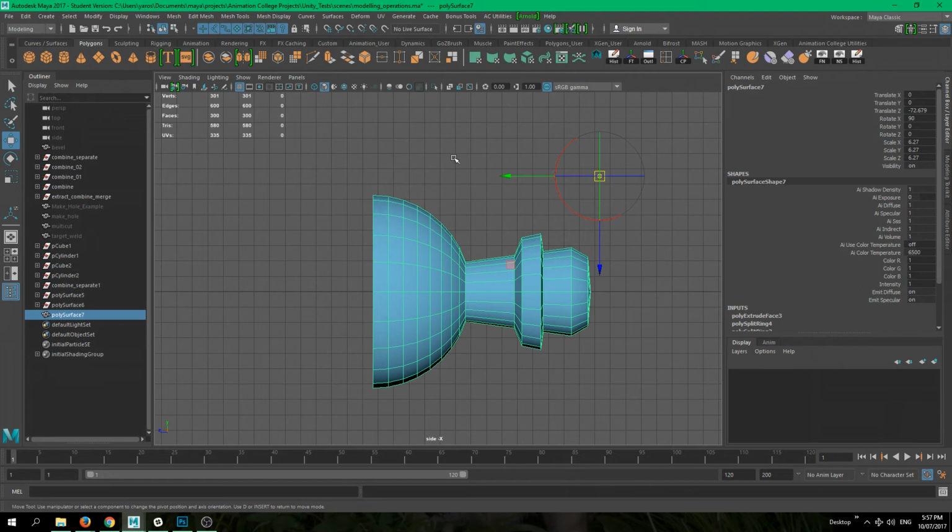For this, first you need to confirm which axis you're working with. And that's really easy to do. All you have to do is drag using one of the arrows. So I've dragged it left and right, meaning that I will be working with this particular axis, which I think at the moment is our X. Then press and hold V for Valerie. And now, if we start dragging this around, you will start seeing that it sort of snaps.